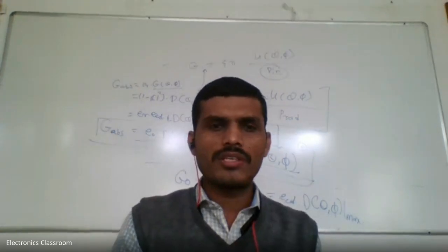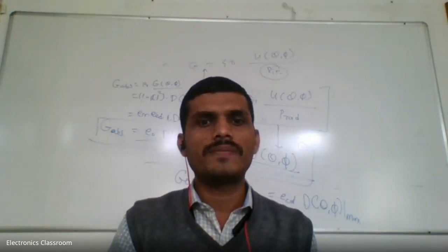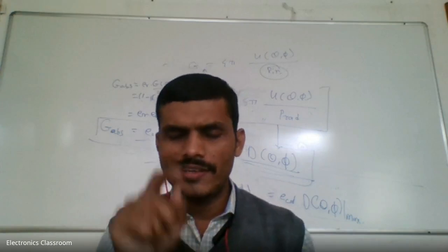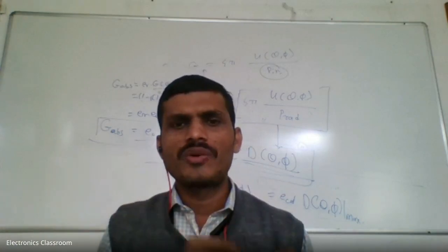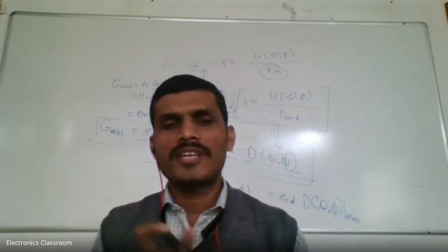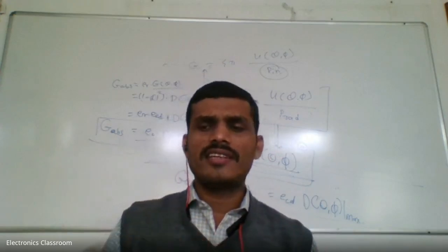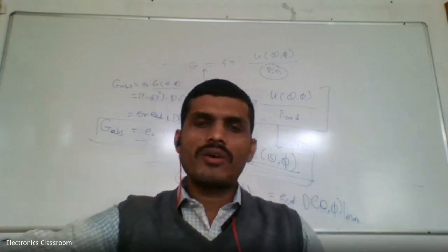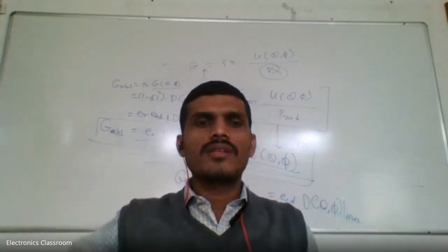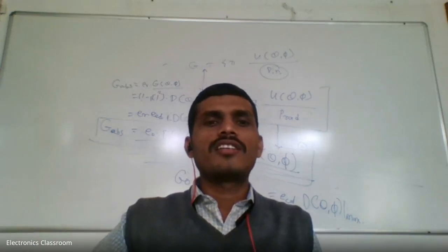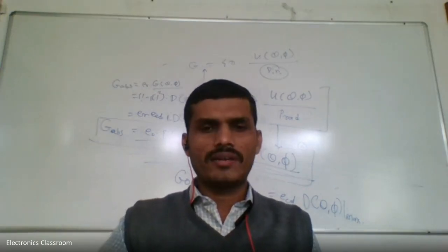So these are the equations related to the antenna, and your G0 can be calculated by using G theta plus G phi. That is, the maximum gain has two different partial gains, G theta and G phi, from the two different components.